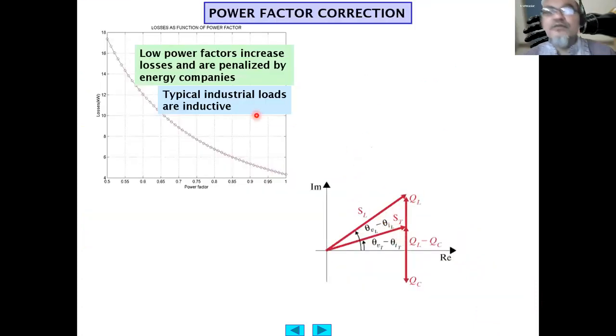Okay. So now we move on to a new concept called power factor correction. As we have learned from the power factor concept in the previous section, when the power factor is much less than 1, we will have a lot of power loss in the transmission line. A low power factor at the load will increase the loss, because the IRMS will be high. When it is multiplied by the impedance of the transmission line, the power loss becomes high as well: I squared times Z of the line, the impedance of the line.